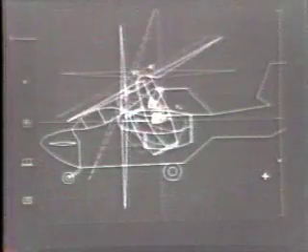Now the designer has selected a pair of links for a mechanism and is exploring the analysis of this particular choice of a linkage. As you see, the mechanism moves the rotor exactly through the 4 design positions, but it has a little unwanted dip as it goes between the design positions. The synthesis only ensures that the mechanism can move exactly through the design positions. To determine the performance between the design positions, one must go through the analysis process.